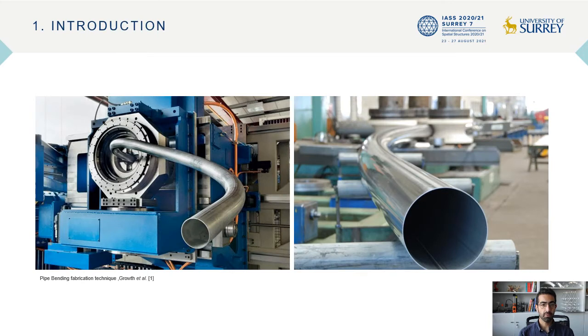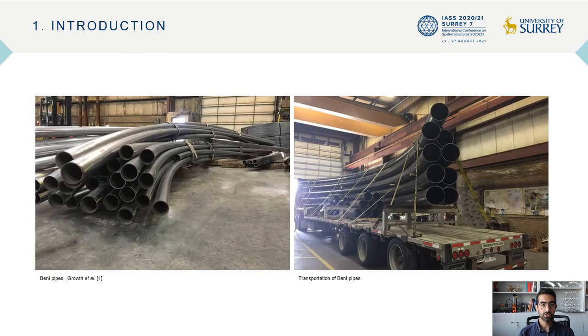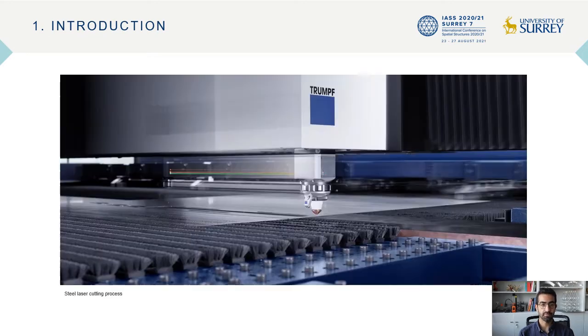One of the most common manufacturing techniques for especially curved parts is 3-roll push bending, which is a kinematic forming process. Bending the standardized profile without a shape deviation to the target geometry is not possible due to the spring back of the material. Another challenge is also final cut, as well as drilling mounting position for connecting elements on the beam after the forming process, which requires scanning tools that makes the process inconsistent and imprecise.